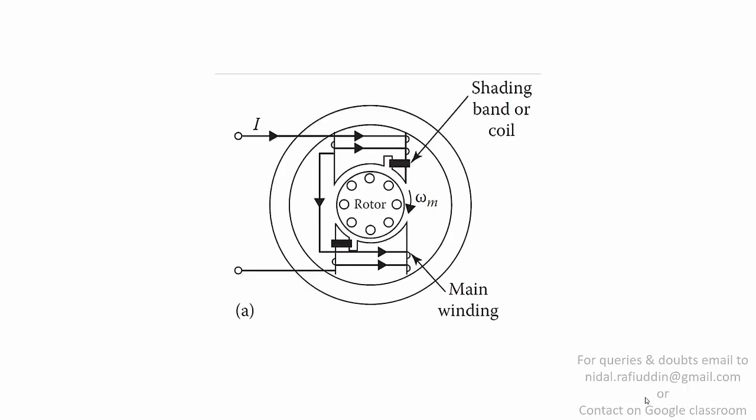First of all, you will need a stator capable of producing a rotating magnetic field, for example this shaded pole type that we have already seen before. Then the next task is to replace the rotor of this motor by the hysteresis rotor. In order to understand the hysteresis torque, let us have a quick recap of the hysteresis loop that you studied in your first year. The rotor can be considered to consist of small elements made up of magnetic material like this.